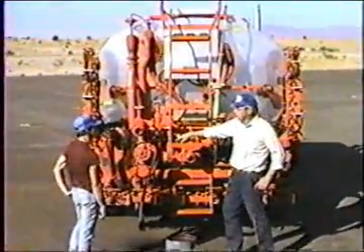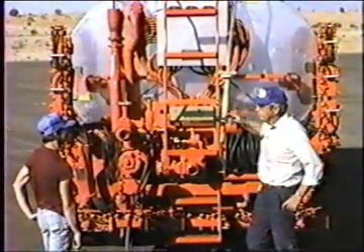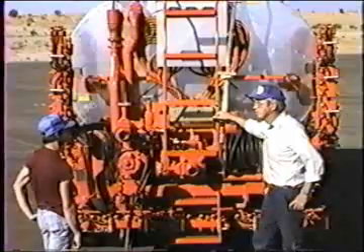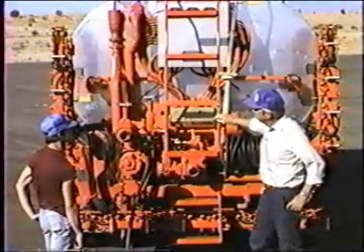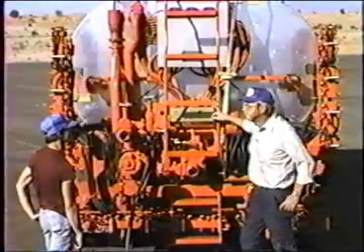When we come to the back of the truck, the pump is going to be running at a couple hundred gallons a minute. It's full forward and it's circulating that fast through the spray bar. It'll be straining a little bit because it works hard to circulate that fast. Material's coming out of the tank, through the bar, back through the relief valve.